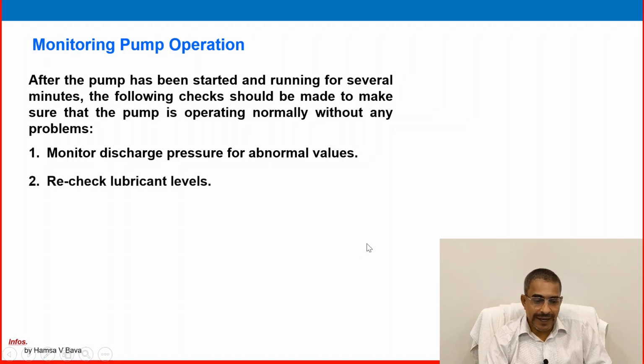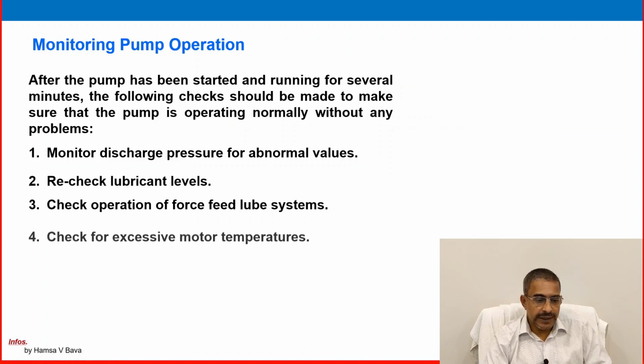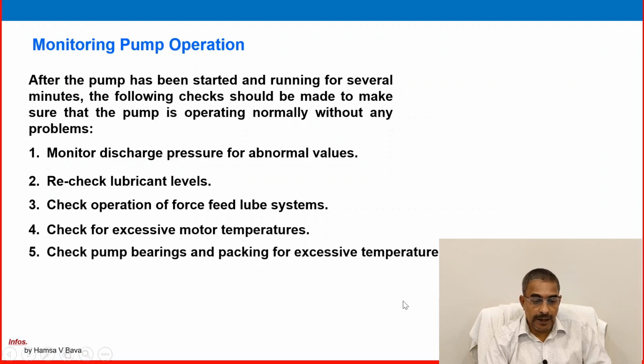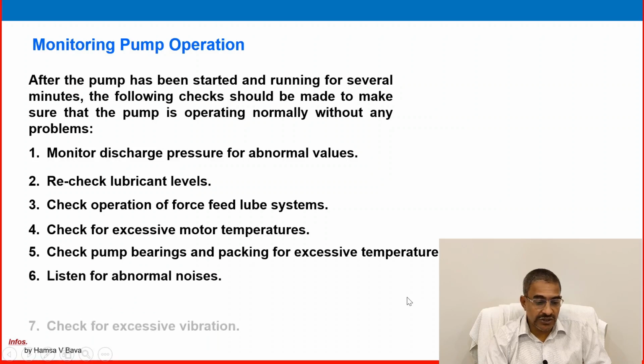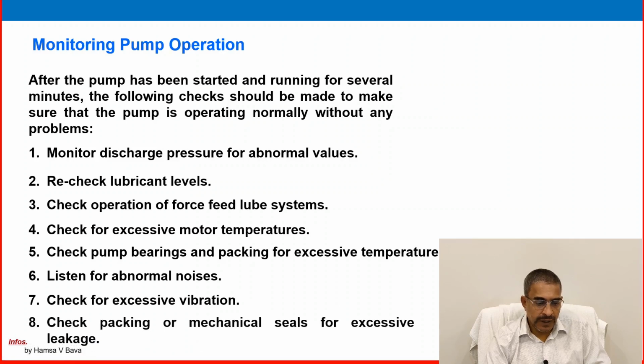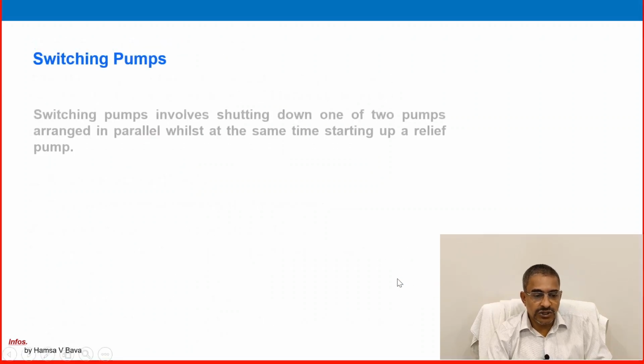Recheck the lubricant level. Check operation of the force feed lube system. Check for excessive motor temperature. Check pump bearings and packing for excessive temperature. Listen for abnormal noises. Check for excessive vibration. That is also very important. All these points are very, very important, and you have to take care of them during startup or changeover of the pump. Check packing or mechanical seal for excessive leakage. Switching the pump.